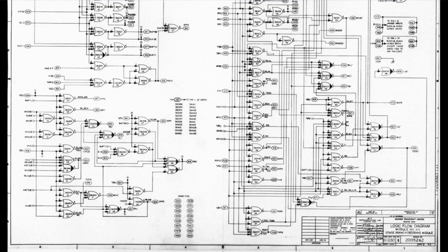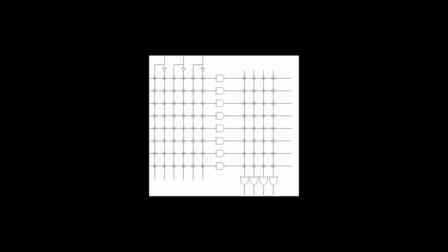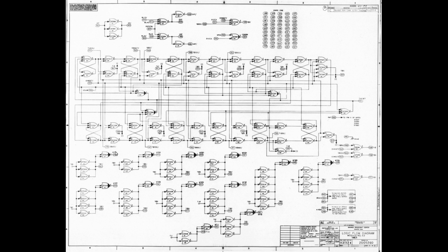And so these are all the same type of integrated circuit, and they're doing these things that we just saw we can do using the universality of a NOR gate to create different types of logic gates. And you'll also find in other parts of the schematic these cross-coupled NOR gates, which we're going to talk about in the next class. These are memory elements, and we'll actually work out the design for a memory element using NOR gates, but we can also do it using NAND gates. And so they built everything out of these single types of gates. So NORs really are universal, and beyond being theoretically interesting, sometimes that's been a practically useful characteristic.